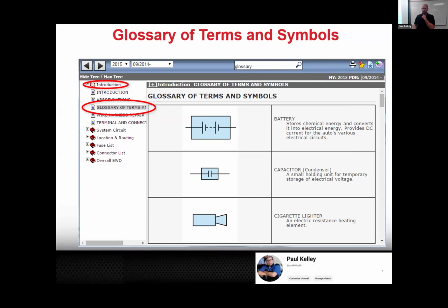For the most part, the symbols are similar enough where if you learn one symbol, let's say this is a Toyota symbol, and then you jump on a Ford, probably the symbols will be pretty similar. But once in a while you'll jump on something like European and it'll be like, whoa, what the heck symbol is that? Just so you know, you don't have to memorize every symbol. Somewhere in that service manual there'll be a key where you can actually look up what each one of them means. And then it's very common as well for unique things to be labeled.